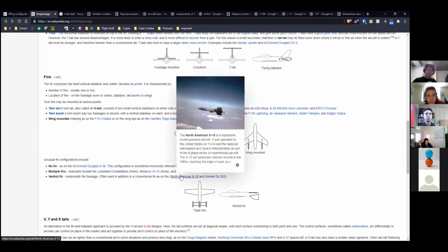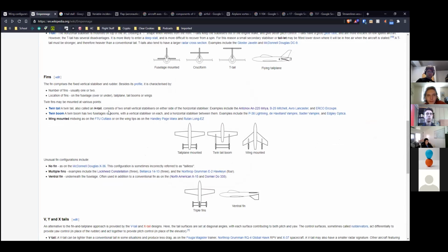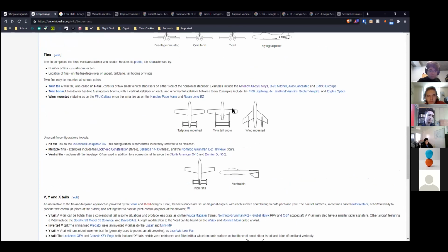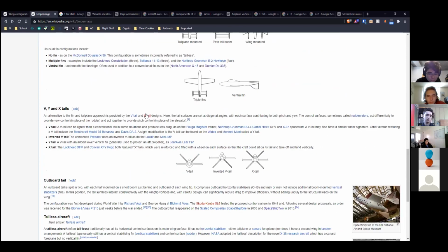So I know why you would do it on the X-15, which is on re-entry, basically. The top vertical is basically completely masked by the body at high AOA. So maybe it's only good for high AOA applications, but then the Reaper also has it, and I don't know why. Or not the Reaper, the Predator. One of those has a ventral V-tail, but it's a weird aircraft anyway. So yeah, and then booms and stuff. I'll talk about that a tiny bit at the end.